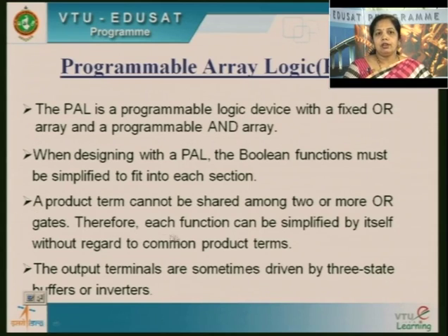Therefore each function can be simplified by itself without regard to common product terms. We should not share one product term among two or more OR gates. Care should be taken while designing this. The output terminals are driven by buffers, so the output of this PAL device is connected to a buffer.